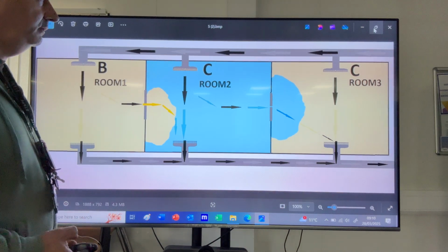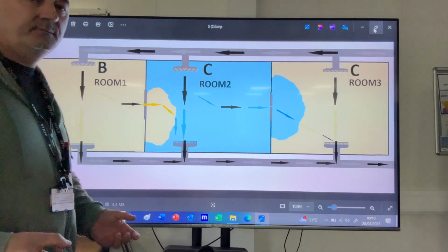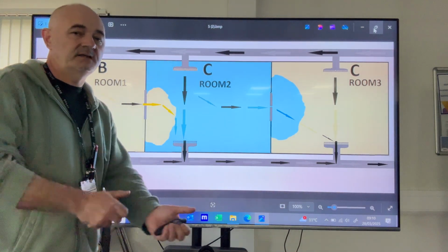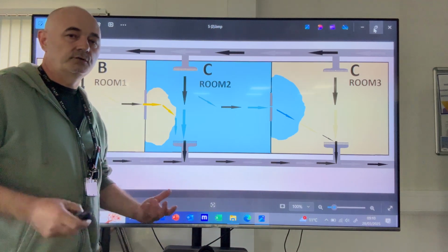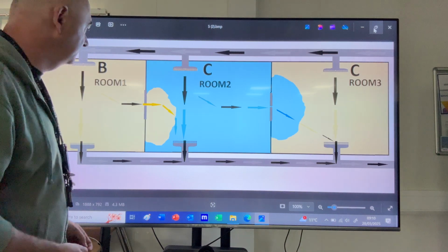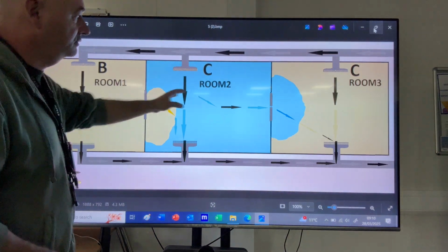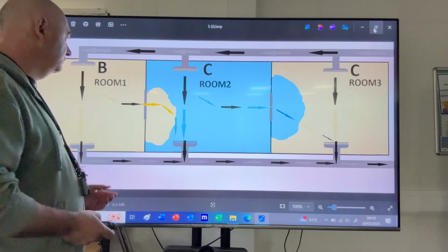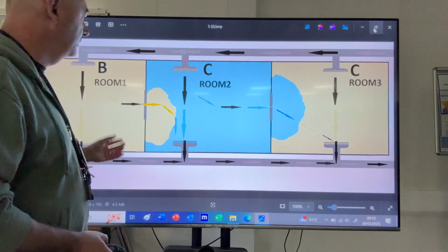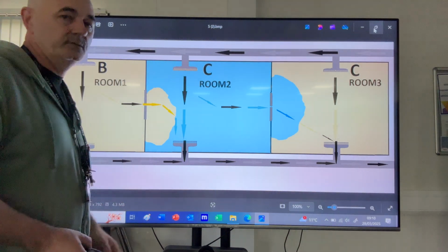Another issue I struggled with when I was employed in 2019: I asked about door control philosophy, the door usage strategy, and I explained that even if the cascade is correct, if we have excessive leak from one room to another, we bring not only the air, but we bring moisture and temperature with the air.